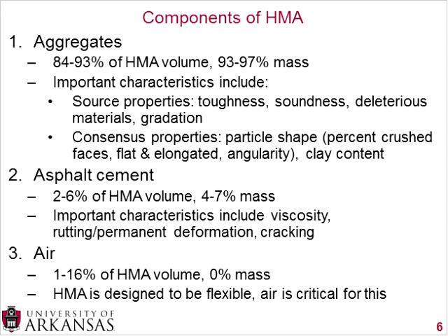And as I mentioned in the previous slide, hot mix asphalt is designed to be a flexible pavement, and the air is critical for this. So changing the amount of air or changing the aggregate structure, the asphalt cement type, these can all contribute toward the flexibility of the pavement.